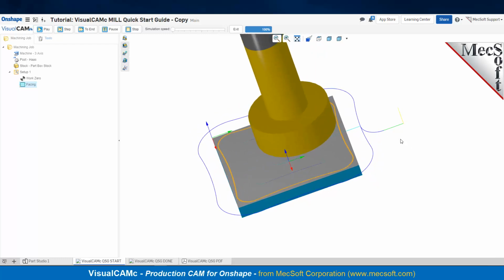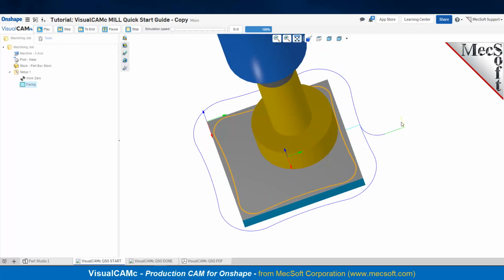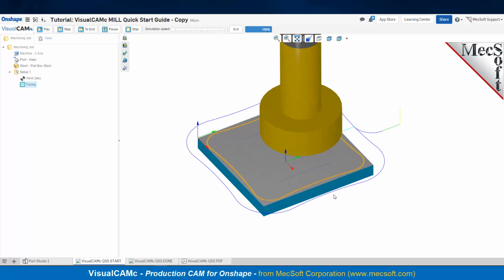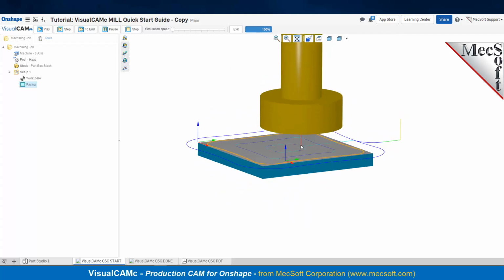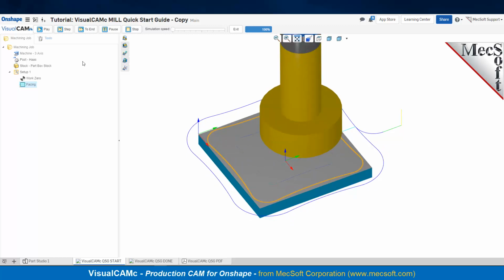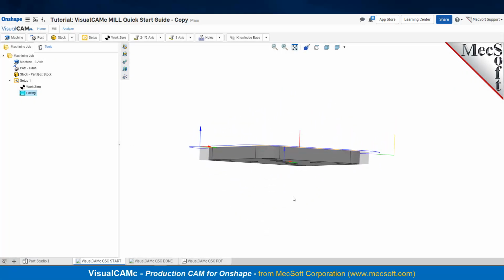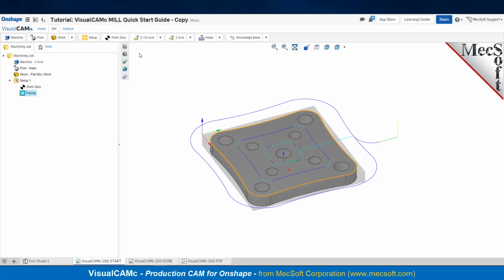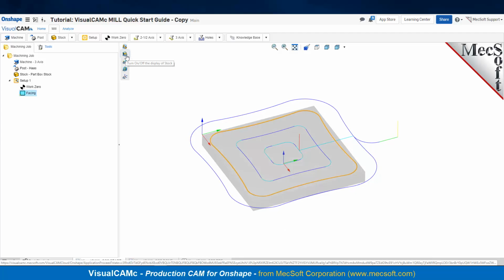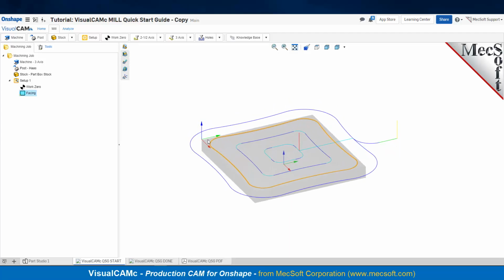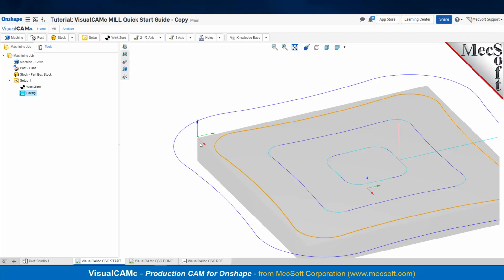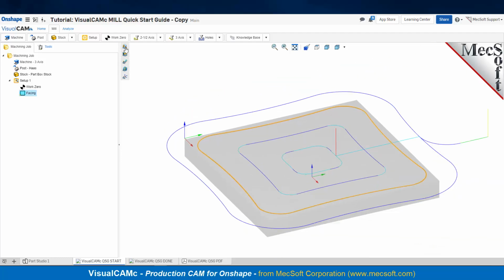So you see that we have our radial approach plunge here, and our approach, and then our radial engagement, and it follows the shape of the part. And then for exit, we're just retracting straight up off of the part. Okay, so let's go exit out the simulation tab. So you see now that the in-process stock is shown on the part. There's our in-process stock right there. So we machined it down from our work 0 location down to the top of the part.